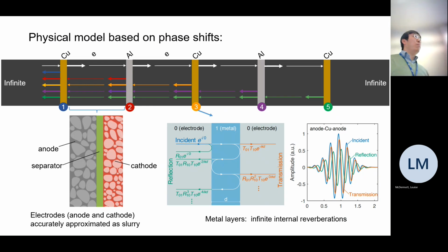So that slurry model means that you averaged the bulk modulus of the solid and the liquid parts according to the volumetric weights. So the bulk modulus as well as the density are averaged in that, and they were found to approximate the wave speed very closely. I think less than 1% of difference compared to experiments.